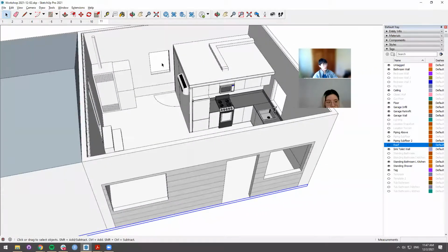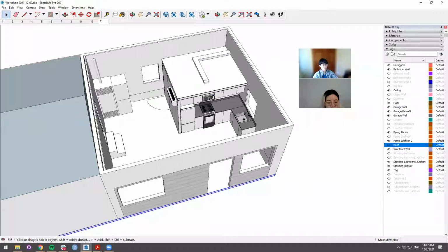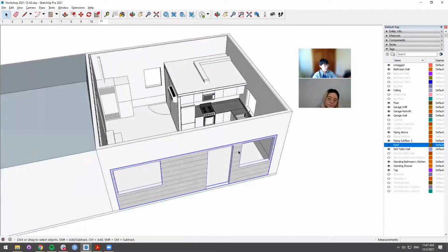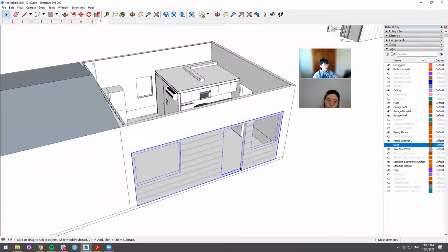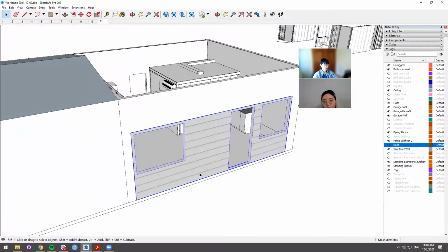And since you were dealing with potentially not a lot of windows in the existing garage, and maybe not interest in putting more windows because that might involve structural engineers, we've been able to go through without any structural engineering stamp in this project. Then this one, you would want to probably maximize the amount of windows you get in there. And there's an architectural question of whether you go through the effort of having the exterior finish of this infill be matching of the existing house, which is probably stucco in this area, or for practical and creative decisions, to intentionally make this finish different than the rest of the house.